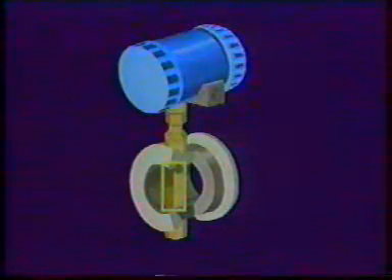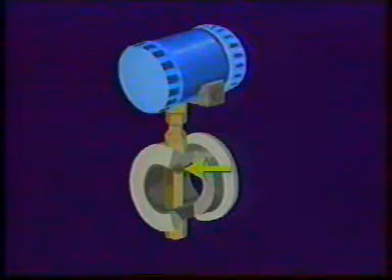After some length of travel past the obstruction, well-formed vortices occur in the fluid. The frequency of these vortices is linearly proportional to the fluid velocity. This phenomenon has been known for years, but only recently has it been used to detect and measure fluid flow. Vortex shedding flow meters are generally comprised of three basic parts. They are a vortex generating element, in this case a bluff body, a sensor to sense the frequency of the vortices and produce a signal that can be measured, and finally, a transmitter to amplify and condition the signal.